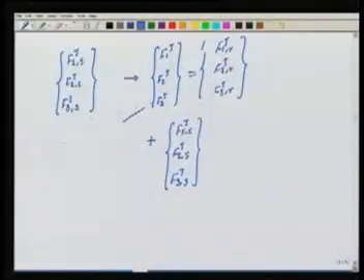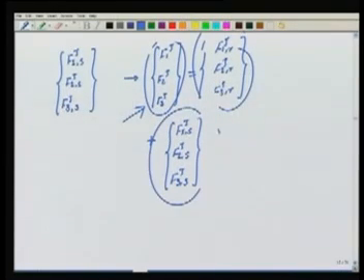Okay. In general, before doing the calculations in the element, I will obviously initialize these vectors to 0. After doing my integrations and so on, these vectors will have some entries, and I simply add them up and I am done. So now I can actually obtain all the information about the Neumann boundary conditions at the element level itself and add these contributions to the element load vector in one shot. Once I have that, I have all the information that I need as far as the Neumann boundary conditions are concerned.